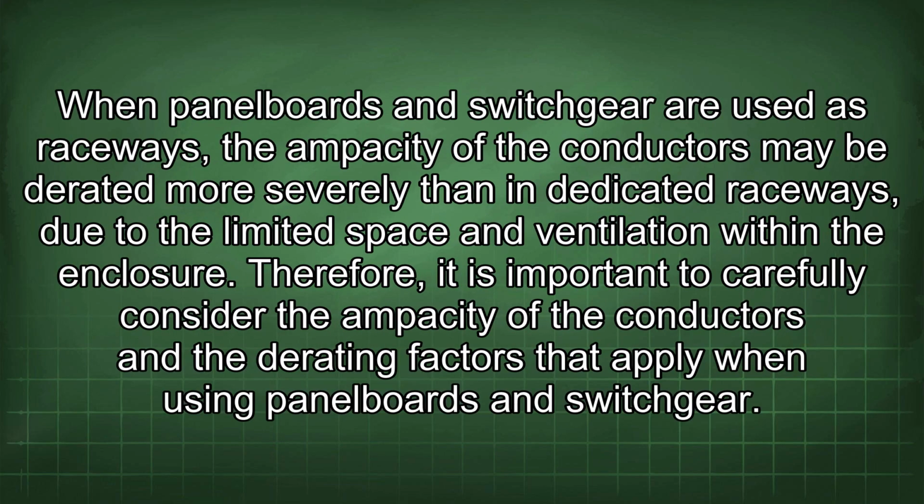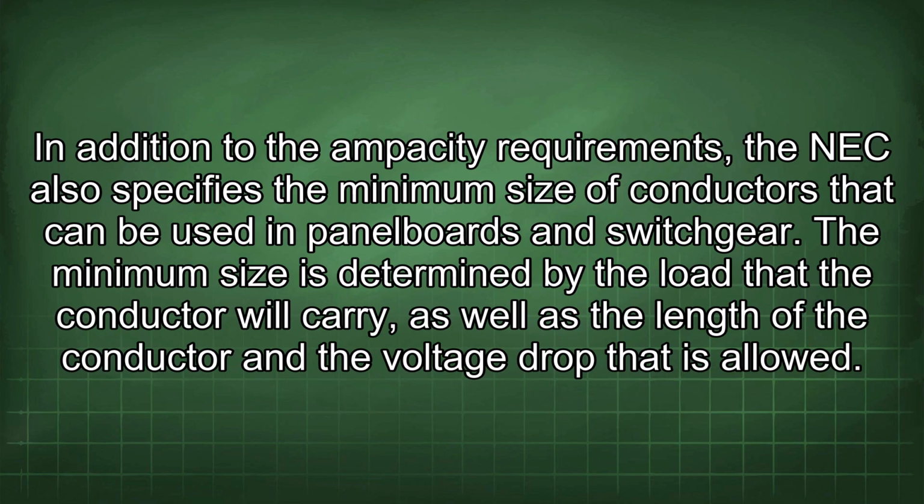When panel boards and switchgear are used as raceways, the ampacity of the conductors may be derated more severely than in dedicated raceways due to the limited space and ventilation within the enclosure. Therefore, it is important to carefully consider the ampacity of the conductors and the derating factors that apply when using panel boards and switchgear. In addition to the ampacity requirements, the NEC also specifies the minimum size of conductors that can be used in panel boards and switchgear.